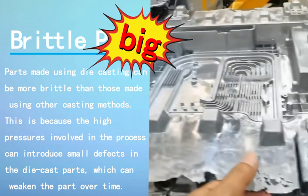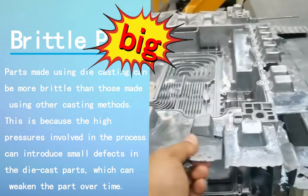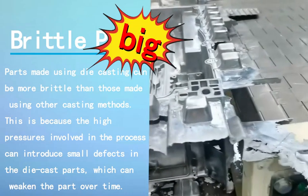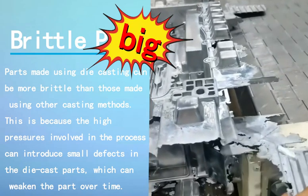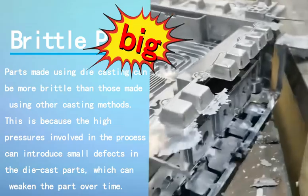Brittle parts. Parts made using die casting can be more brittle than those made using other casting methods. This is because the high pressures involved in the process can introduce small defects in the die cast parts, which can weaken the part over time.